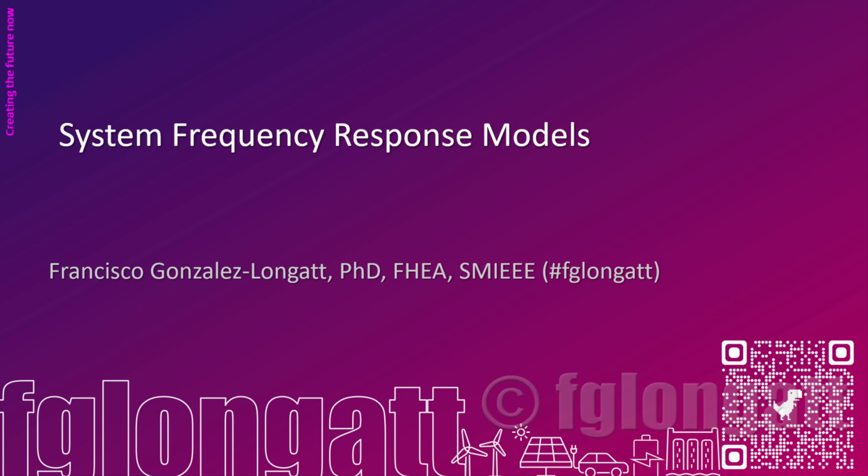And in that video, I explained to you that when you are interested in the frequency response in traditional power systems, I mean, based only on synchronous generators, you can use those linearized low order models. So today, the video is extremely practical, because what we want to do is to show you how to implement one of those system frequency response models inside one modeling and simulation software.